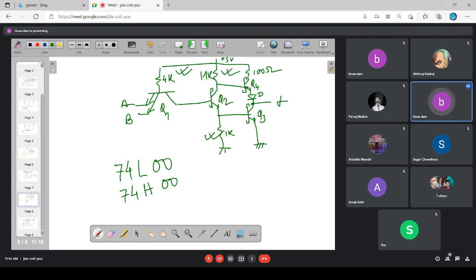That means the TTL gate can now operate with lower power dissipation. That particular series of TTL gate, where I introduce Schottky transistors as well as increase resistances to reduce the power dissipation, is called 74LSNNN. This L stands for low power device. Low power device, how are we ensuring that?